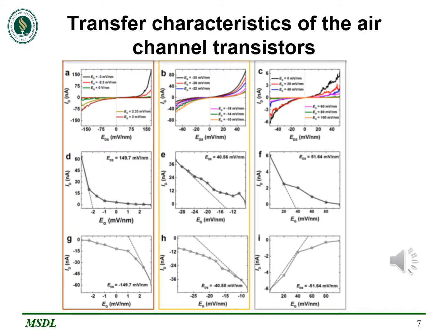However, in negative bias operation, tungsten and gold-based devices turn on with increasing positive gate voltage, whereas it turns off in the case of platinum. This difference is mainly due to the tunneling mechanism that the respective metal air transistor experiences.